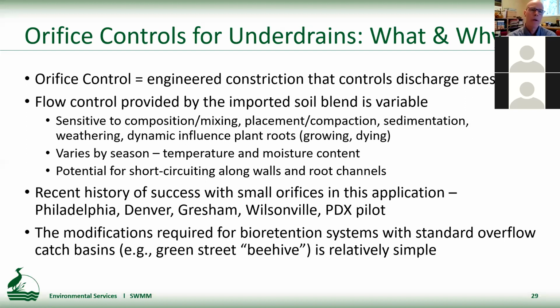Again, we aren't the only ones doing this. Philadelphia in particular has a long history of success with small orifices on the end of underdrains for bioretention systems. Denver's also doing it. Gresham is doing a lot of testing, I think as retrofits on the underdrains for bioretention facilities. We're seeing them in Wilsonville. And then we've had a pilot that we've been monitoring since 2016. I just wanted to note that, as you'll see, the modification required for bioretention underdrains is, in many cases, a simple modification if there's an overflow catch basin or structure such as the beehive that we use in our green streets. Next.